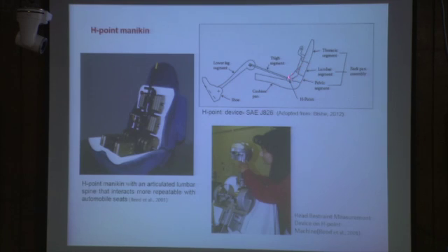According to the standard, this is a representation of the body form of a 95th percentile driver. This is the upper body, the trunk portion, this is the thigh portion, and this is the lower leg. This is the location of the H point. This is the pelvic segment, lumbar segment, and thoracic segment.